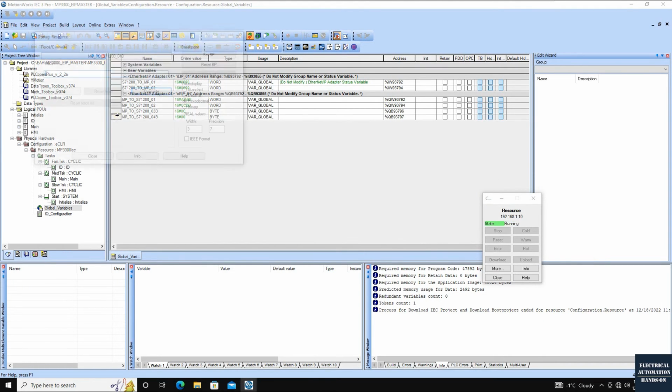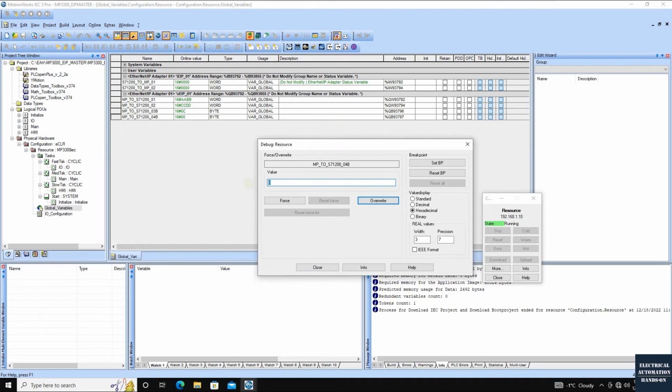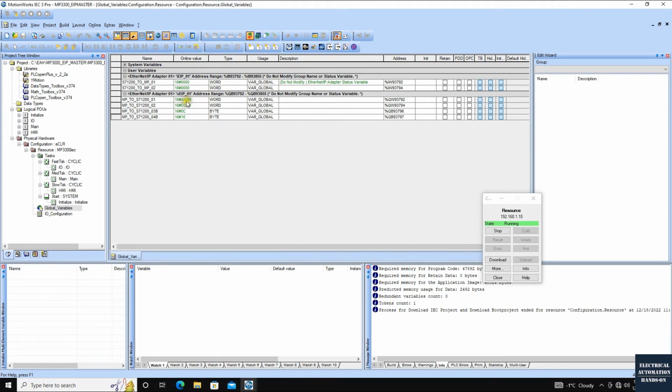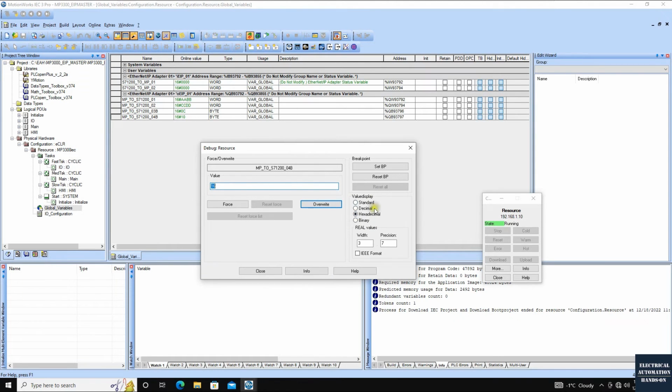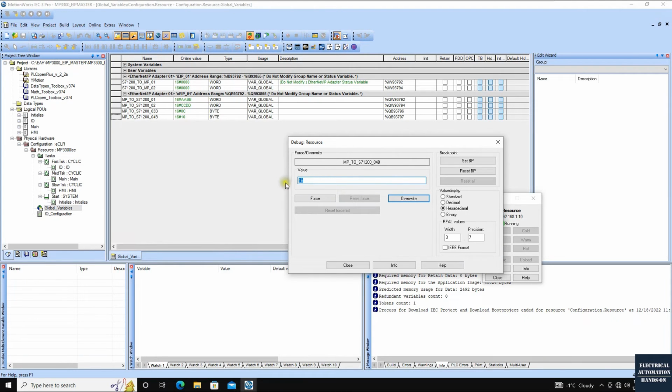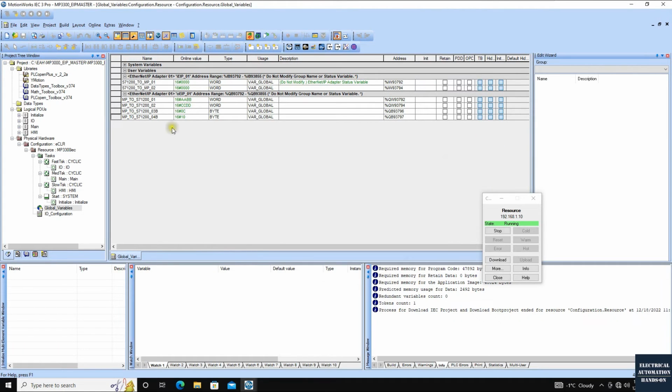Okay. For this one, I can change to the 16. 16 should be 10 on the hex. Okay, 16. So I'm selecting, and this is the decimal. I can click the. Okay, the decimal. Okay, here the monitor, this value display that represent the display at here. But when you read the data, you need to tell the system default this is the decimal. If you are going to change the hex value, you need to type in the 16 pound and write AABB, for example. Okay, so we prepare the data at here, and now let's shift to the Siemens side.